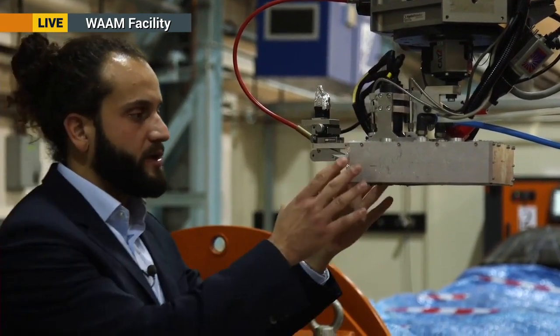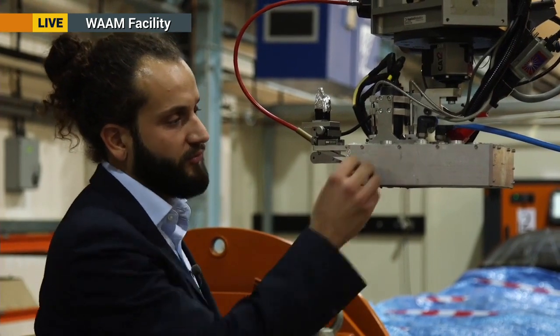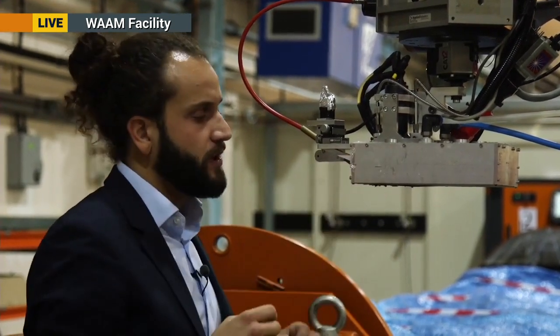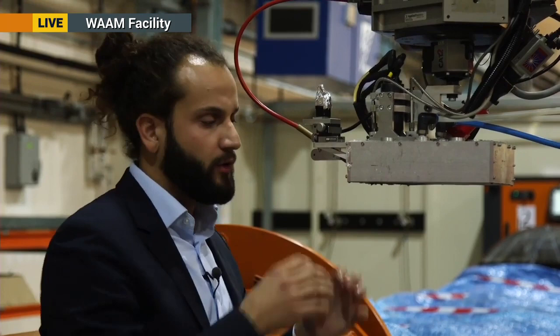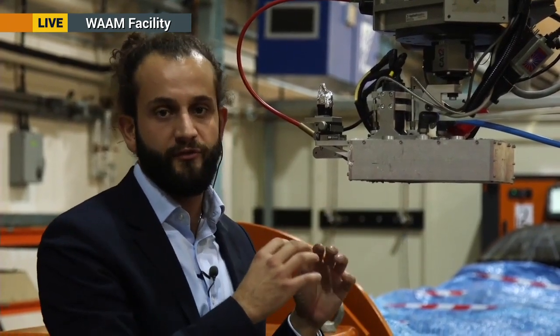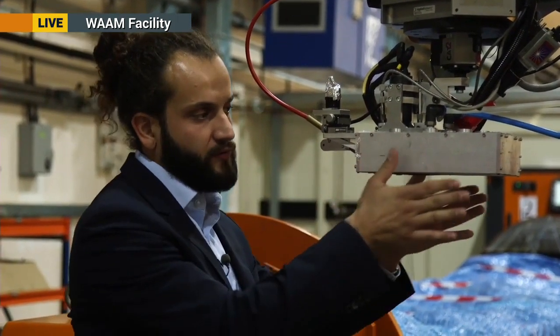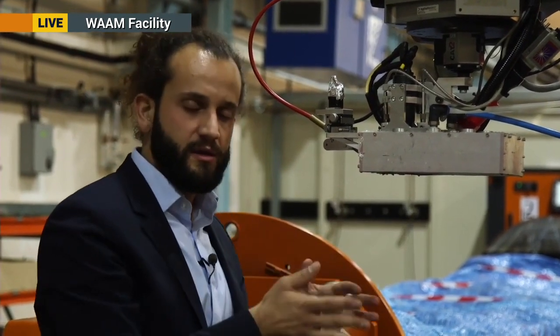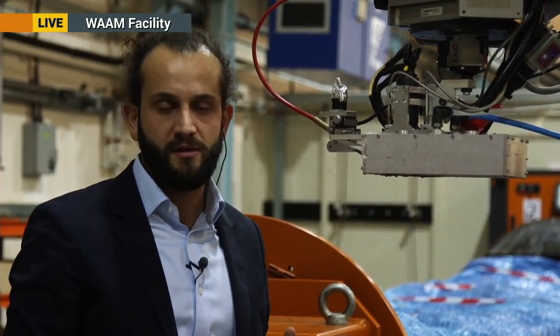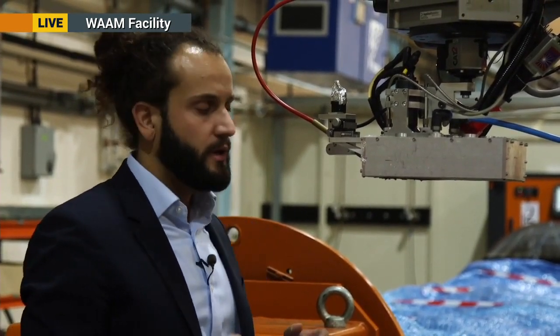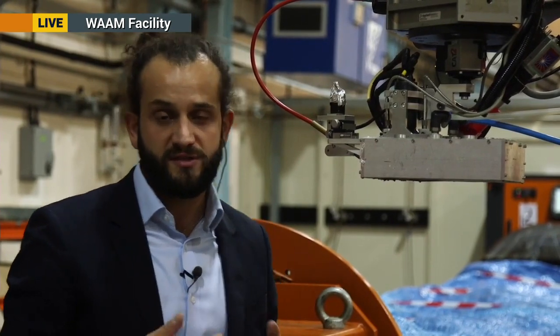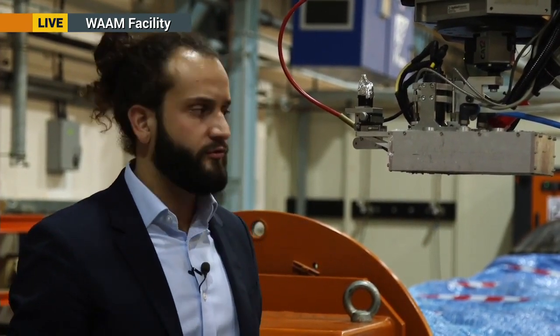So we developed this box, which thanks to a clever design of plenum chambers and laminar flow tubes, produces that inert atmosphere only where the material is hot enough to need it, therefore at the bottom of its surface. And once the shielding device has moved away, we know that the material is cold enough not to get oxidized, therefore not pick up oxygen anymore. And in this way, we've been able to print structures for fast jets, for example, Typhoon, that were over 2 meters in width and 1.5 meters in length, which is again a world first.